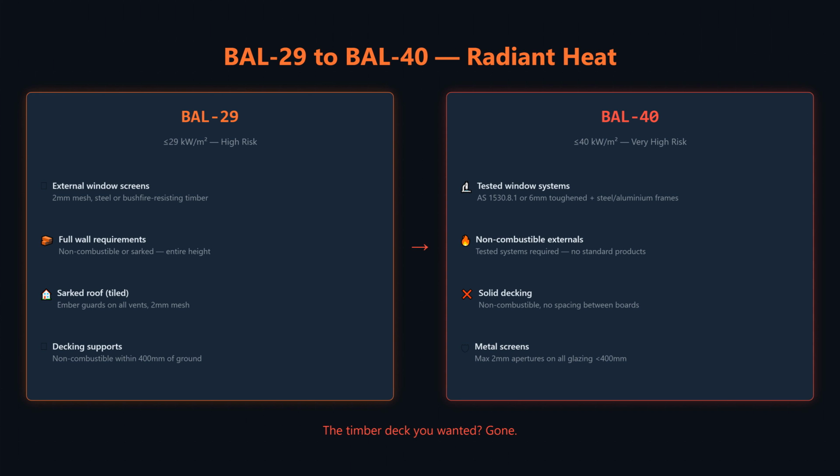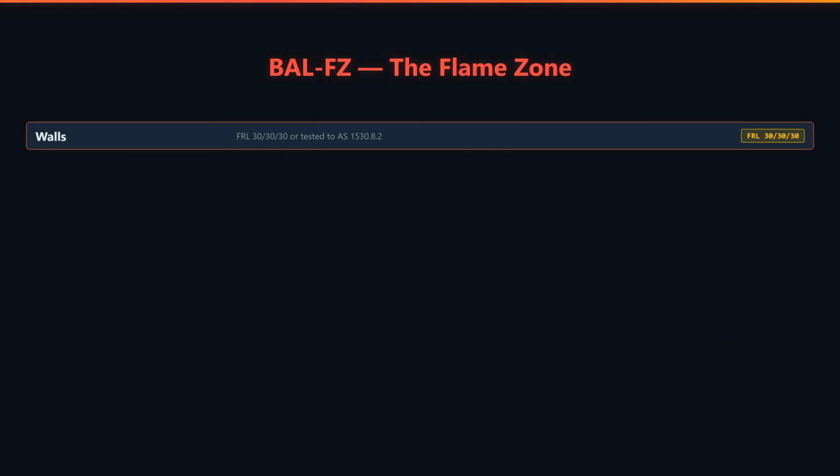And here's something that surprises many builders. At BAL-40 and above, your decking must be non-combustible with no spacing between boards. The timber deck you wanted? Gone.